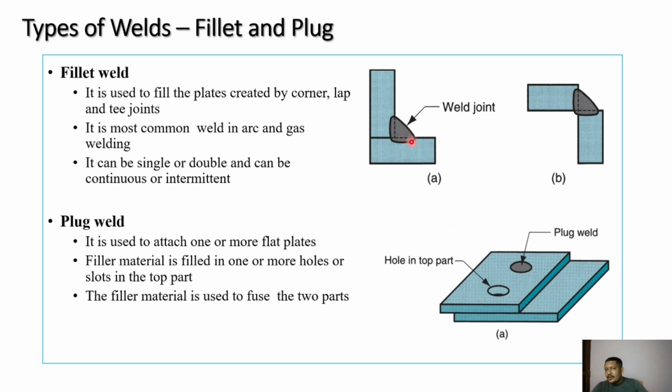So without any grooves on an L shape or a T, normally when you are welding it, we call it a fillet weld. Sometimes if you want more, you can see the penetration is only up to here. If you want more penetration of the weld to take place, again you need to cut the grooves over here, so that in the entire structure you will get penetration. Based on your loading applications, you have to choose those criteria.